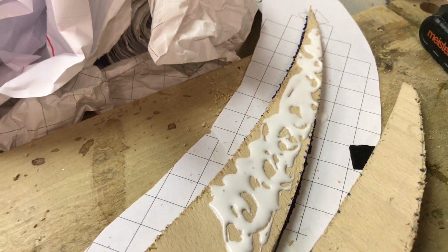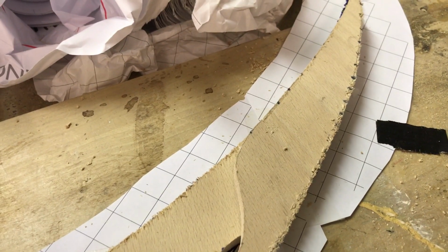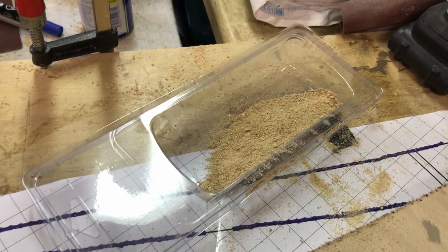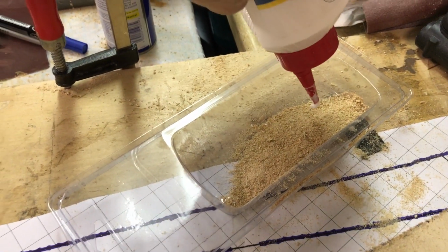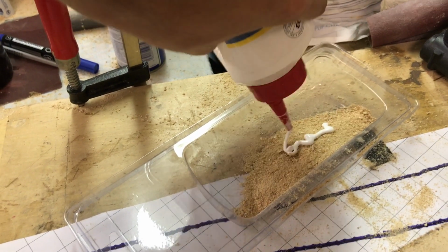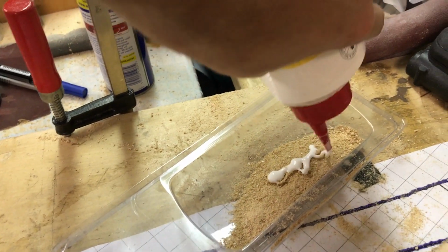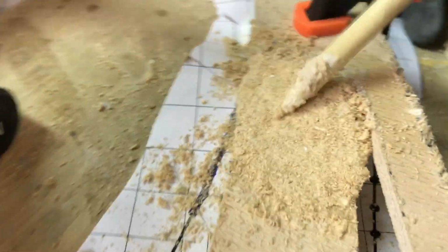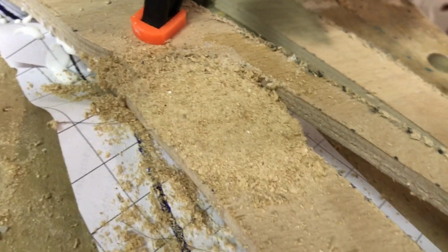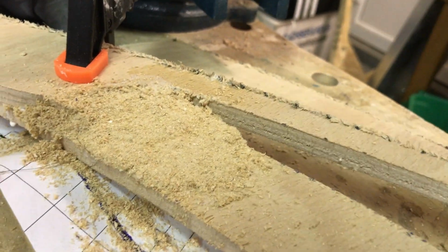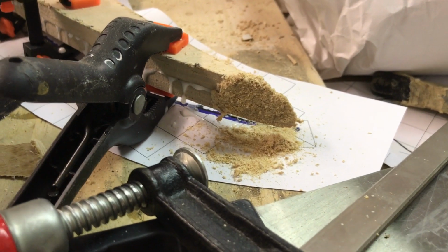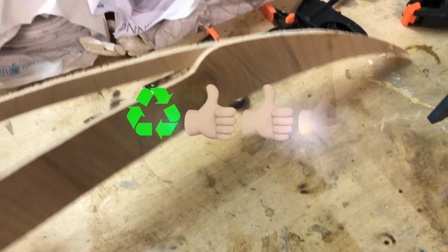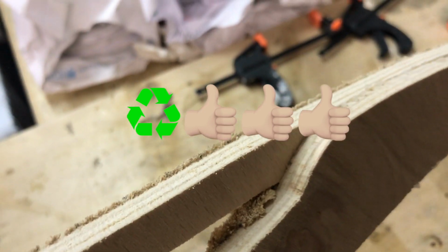After we have done that, we can glue our two pieces together and use some wood filler to fill out the big gap between the upper and lower part. If you don't have some wood filler on hand, or if you're just silly, just like me, and don't want to buy something, then here's a nice trick for you. Don't throw away all that sawdust that you produced earlier and mix it up with some wood glue. This is a perfect wood filler, and once it's completely dry, you can easily sand it down. Yeah, so this is a very cheap solution. And also environmentally friendly, right? The next step is to sand everything down.